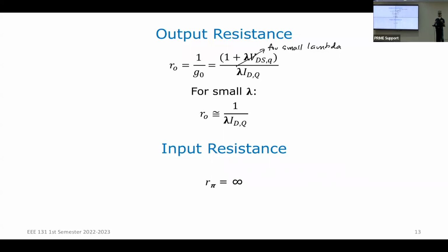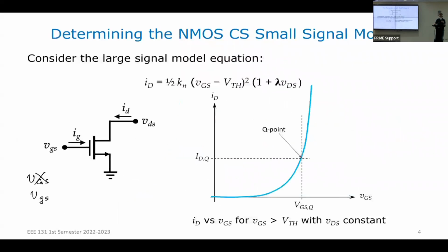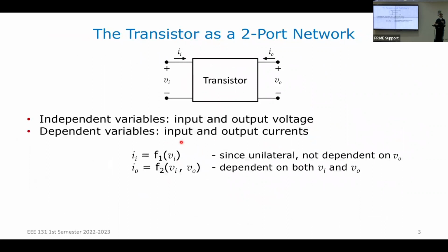The final parameter that we want is our input resistance. If I go back several slides, ito, we want our input characteristics. How do we relate your input current to your input voltage? In other words, for an input voltage, what is my input current? And since this is linear, what we'll model that is a resistor. Kasi it's just a voltage as a function of current and linear. So what we'll model that is a resistor.